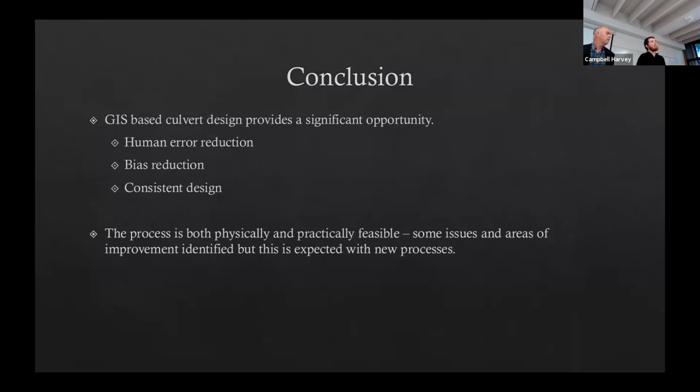Yeah, one of the key things I wanted to do as well was create that repeatable process, because as soon as a designer undertakes the current process, the values that they get differ from person to person. With those TM61 charts, I found when I was using them that even the thickness of your pencil lead and the angle that you have your ruler on can severely impact the result you get. So with those equations, it reduces that variability, and you almost get back to having a unique solution for each catchment, which is what you want.